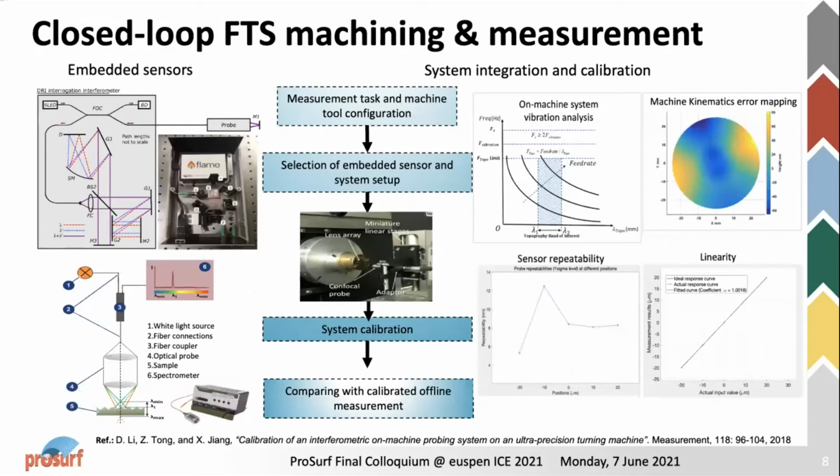The on-machine surface alignment is not just mounting a sensor onto the machine tool stage. Actually, there are mainly three things that need to be carefully considered. The first question is how to select the proper sensors. In general, the sensor needs to be small, performance stable, and capable of capturing the surface features of interest, and have high measurement rates and high data processing speed.